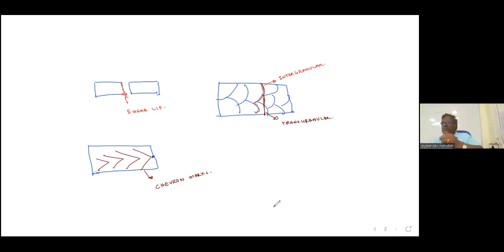Suppose you know the tank or pressure vessel is going to operate in low temperature, we have to choose the material accordingly. So generally for cryogenic, we will go for stainless steel. If you use a normal carbon steel, it can go down to minus 20 degrees centigrade. That is, selection of material is very important.